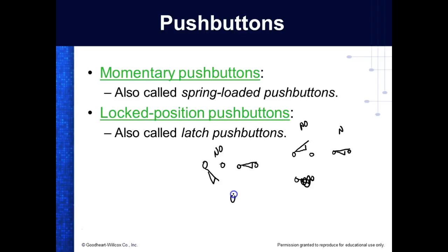If I came over and did this, we look and see what gravity's trying to do with the switch. So what's gravity trying to do? It's trying to open it. So this would be a normally open held closed. If I came over and did this, what's gravity trying to do? It's trying to close it. So it must be normally closed, held open.